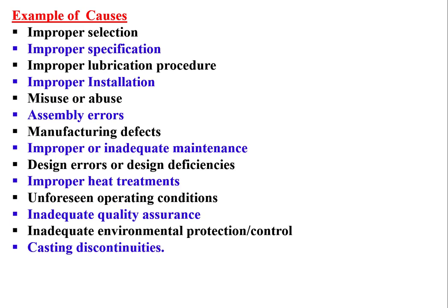Or if we do improper maintenance or improper surface or improper lubrication procedures, improper viscosity of lubrication, improper periodicity of lubrication, improper amount of lubrication, or improper type of lubrication, improper installation, we install it wrongly.